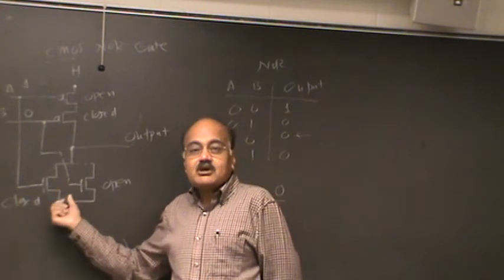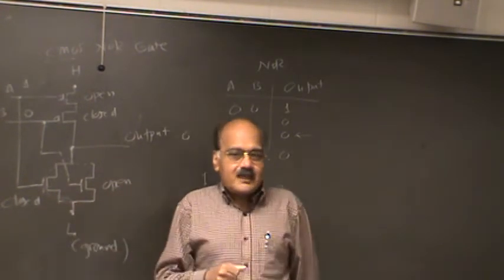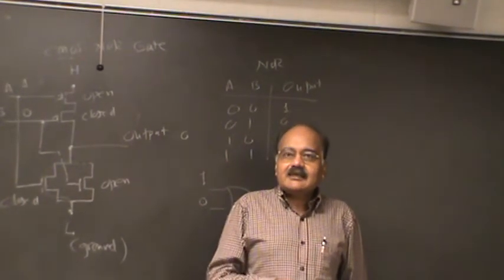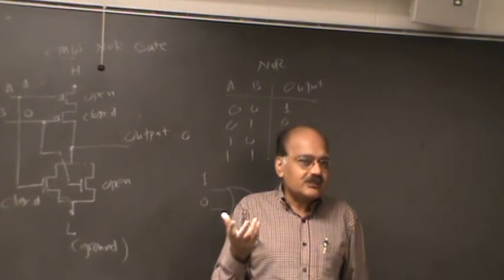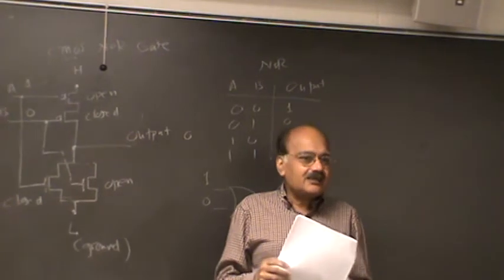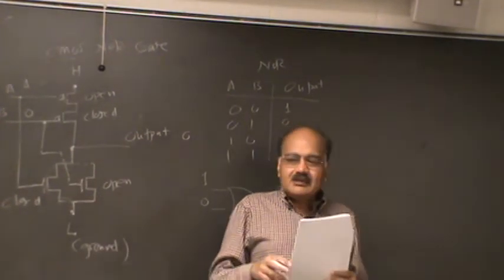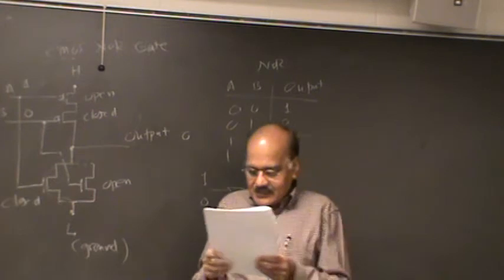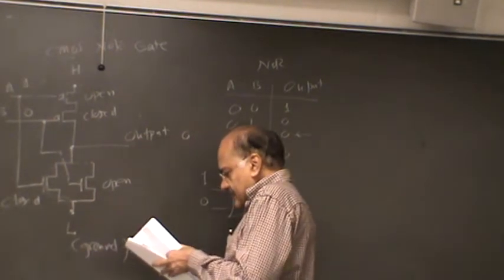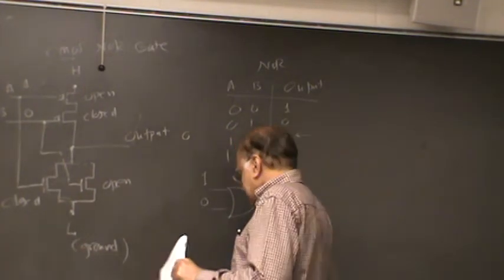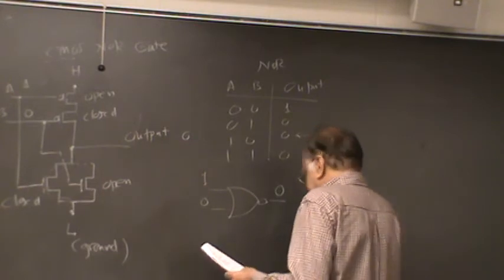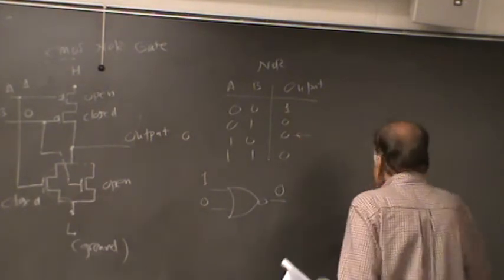And that makes CMOS especially good for high density, because you can put a lot of components there, and as long as they are not switching, it's going to consume very little power. The power consumption would be basically linearly proportional to the number of nodes switching in a CMOS circuit. Okay, and now let's look at the switch level fault modeling, and let's do that here.